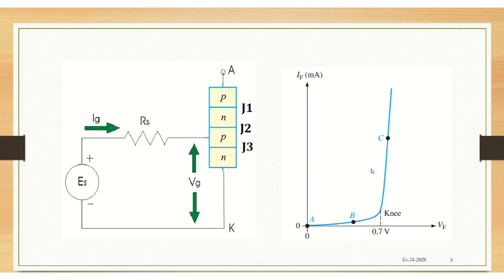Conduction would be fast means the applied voltage would be very less and the current would go high in a short period of time. So you may get the curve somewhere here for the highly doped condition. Follow my arrow. For a highly doped condition, the voltage applied would be very less and the current would rise instantaneously.